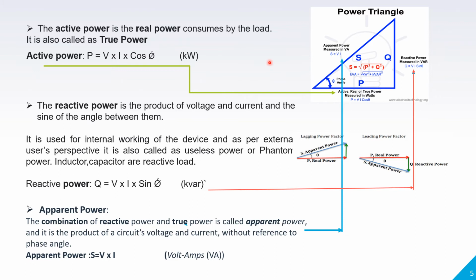This is also called real power. It is also called true power. Whenever we say this is 40 watt, 60 watt or 2 HP, 5 HP, we are always dealing with the active power. Second, reactive power.